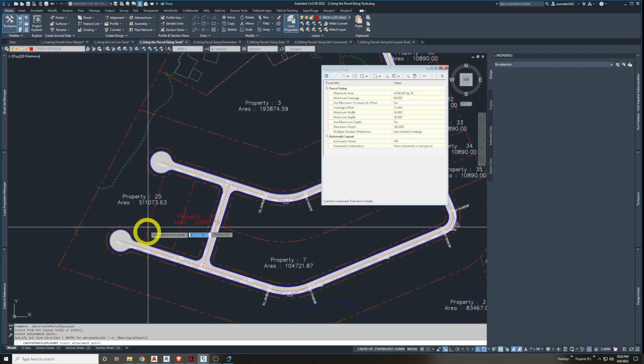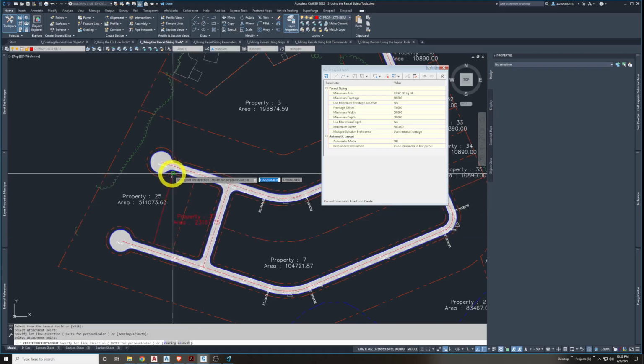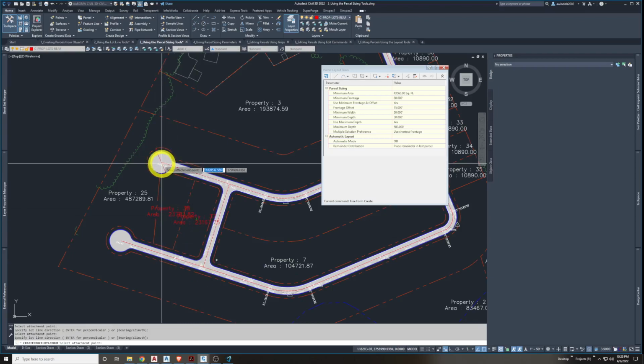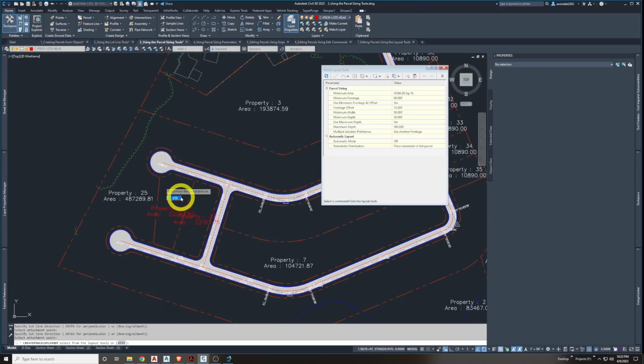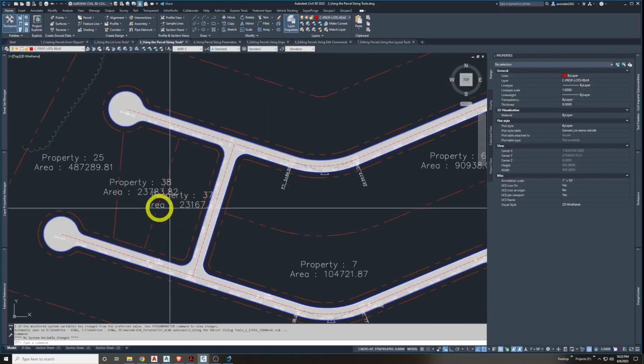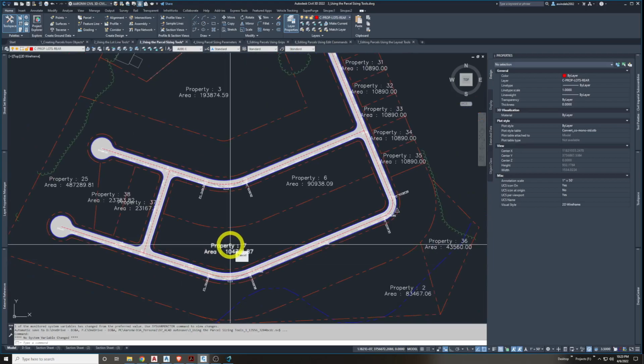So that was a freeform create. Let me make another one here. Pick there. Let me pick to a point. Let's pick to that center. Say I went to the center of the circle, I hit enter, I'll hit escape. I made 2 of them here. I made an extra one. So that was the freeform create. It lets you get a little more creative, moving around, a little more dynamic.